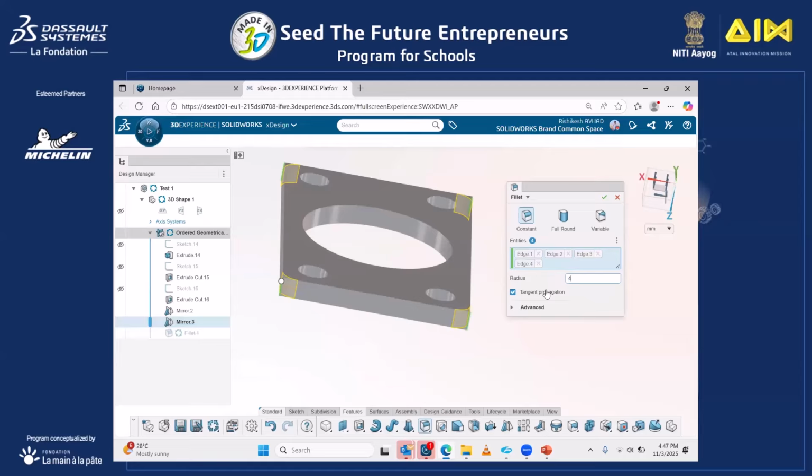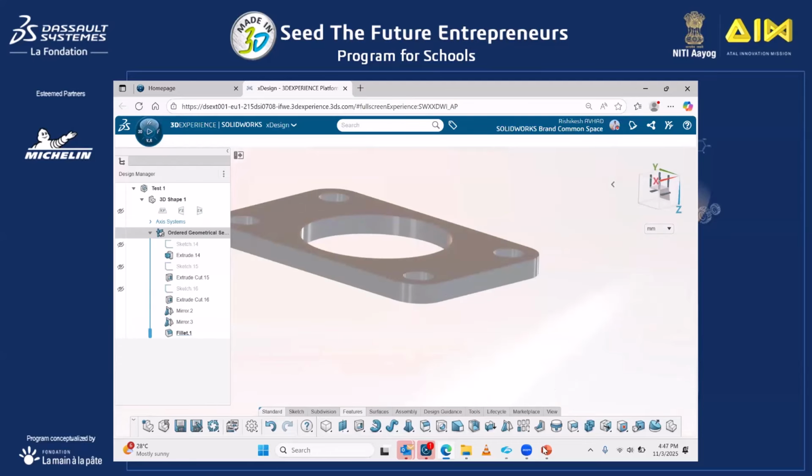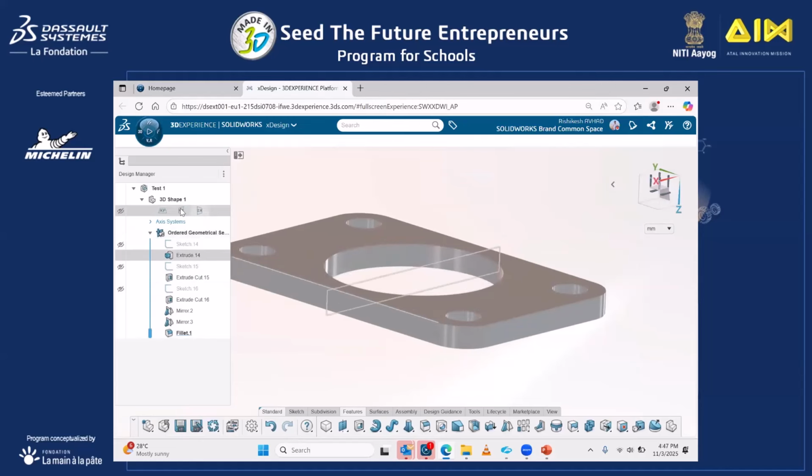20 we don't want, we want it 40 mm. So let's select 40 mm. So the base of the solid model is now ready. We need to make the above portion, so I will now select the YZ plane, sketch.